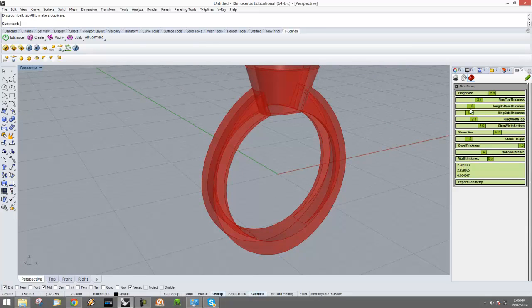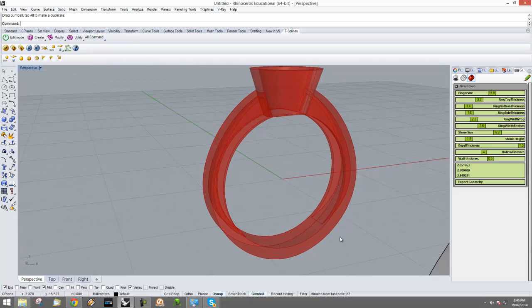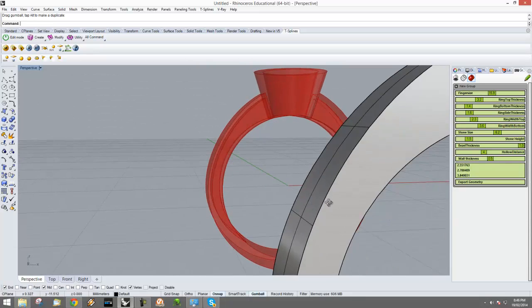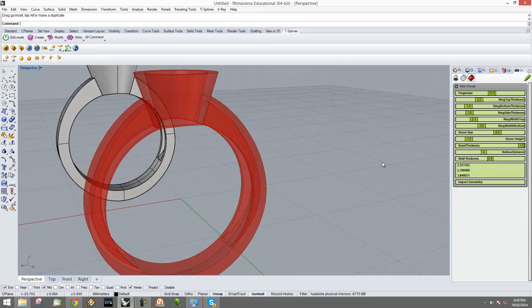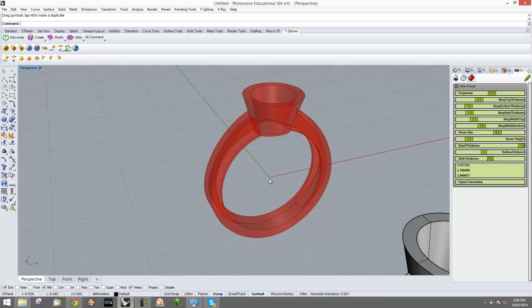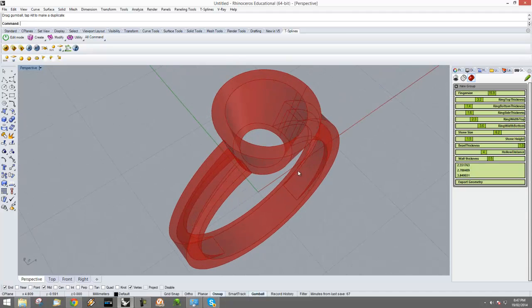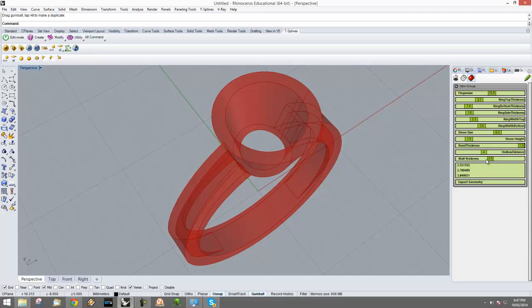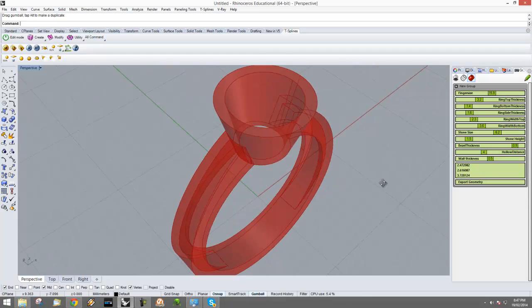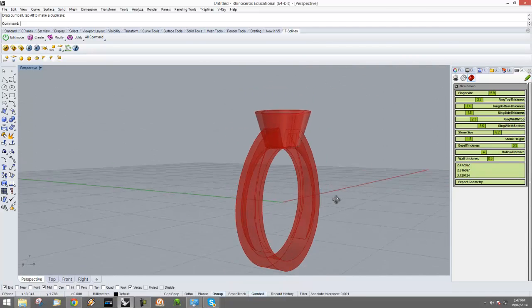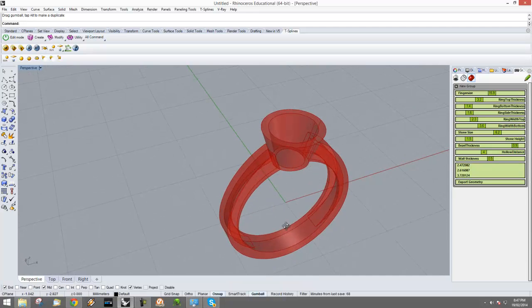Because the next thing we can start looking at is our bottom thickness of the ring, which is currently 1.8, which is quite heavy for mass production. So we can bring the bottom thickness of the ring down to 1.4, and we got to 2.7 grams. As you can tell, we've got 0.2 of a gram to go. Our side wall thickness is 1.6. I don't really want to mess with that. I'm just wondering where else we can steal a bit of weight. Maybe if we make the collet a tad thinner, so the wall thickness on the collet, the bezel thickness, let's bring that down to 0.9. That took 0.1 of a gram. And we've quickly dumped about 1/2 gram on this ring so far without radically altering anything.